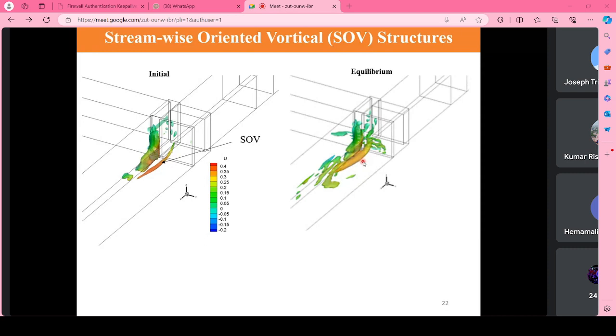This helical cell is very important for the incipient motion, but since the model is using an RANS model, we cannot comment much on the role of the helical cell in the incipient motion. Had we done an LES model or DNS model, that's not very easy. It requires a lot of time and resources, and sometimes is even beyond the scope of the study. Then we would be in a better position to understand the role of the helical cell in the incipient motion in the channel.